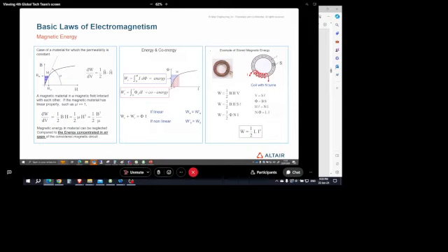So let's move now to the magnetic energy, because all what we say previously and what we are going to do for rotating machine is to canalize this magnetic energy and to maximize it in the air gap in order to maximize the torque. So it's important to know this magnetic energy concept, but it's a really large module, and here I put only few elements.